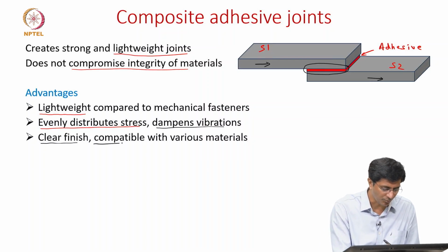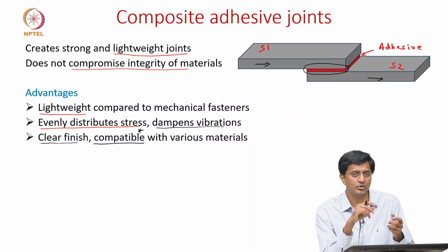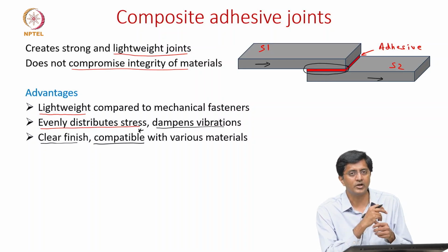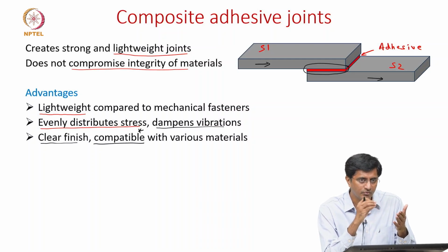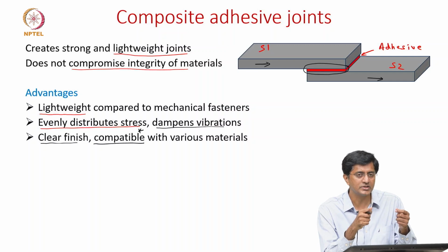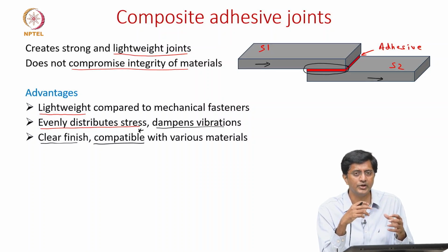This is very important, I would say, because unlike welding, the problem, let's say, in welding of metals is some methods are only suitable for very specific joining. Joining aluminum, let's say, is very difficult because it's not as straightforward as joining steel bars. There we have differences with the melting, so we need to find a welding method which is much more suitable to, let's say, aluminum or any other material.